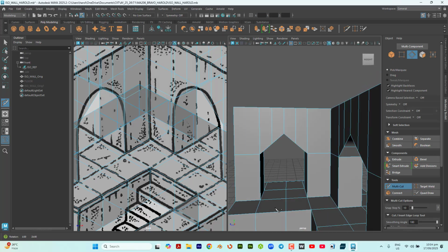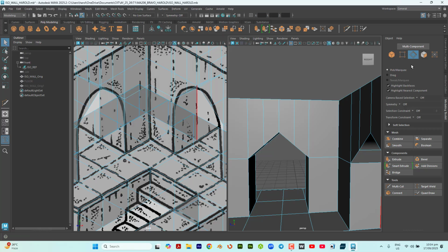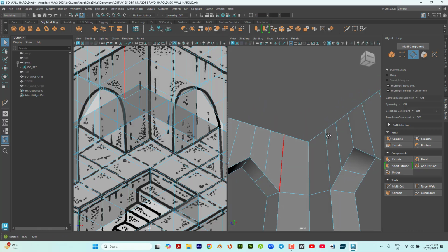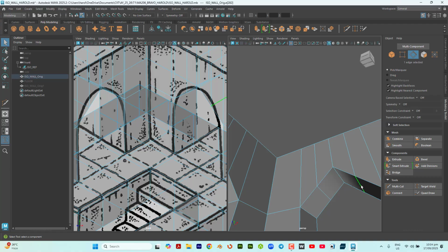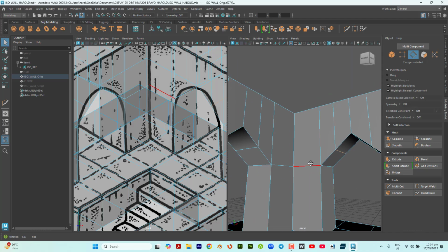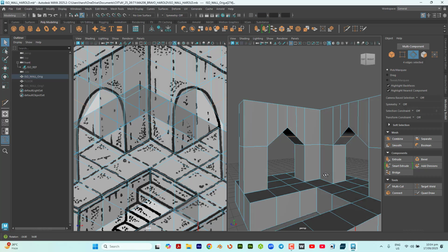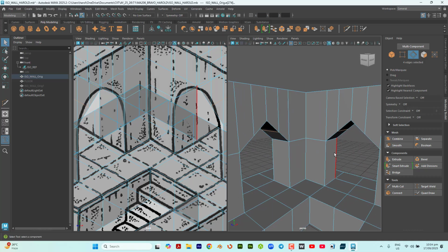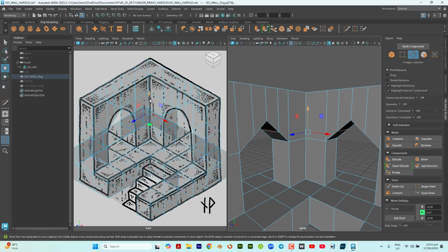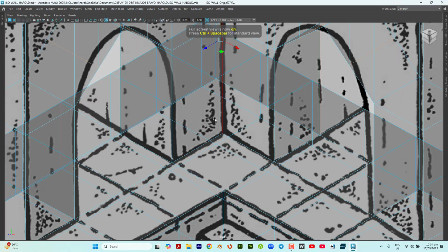And there you go. Switching quickly, turning off the multi-cut tool, switching to the edge selection. I'll select this once more, hold shift, select the other edge once more. And then I'll go to the other side, holding shift, selecting those new edges that I've created, and then I'll just use W for move tool, and then again I will just drag them, control space bar, so I can see here, bigger, there.